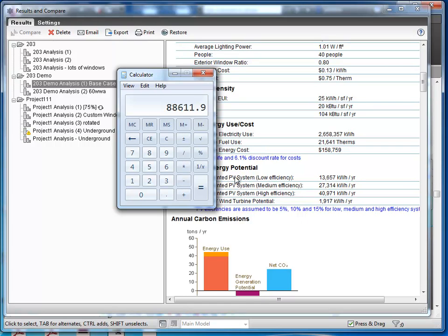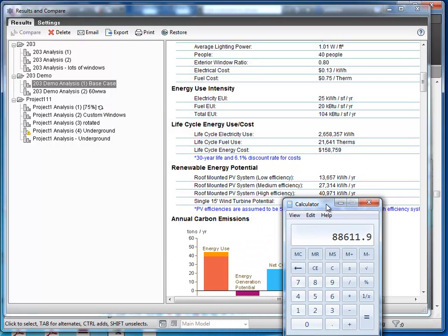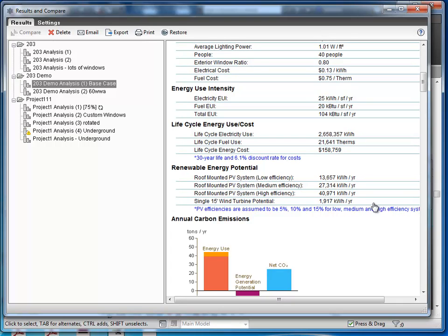Okay? And my PV system here can generate about half of that. So you can see if I could reduce my energy needs so that they were below the 40,000, then I could almost provide enough electricity for my building. Does that make sense? So you could either try to make your roof bigger, or you could try to reduce the energy, which we'll work on. Of course, we will make that better because we're at 80% window wall area right now, which is too high.